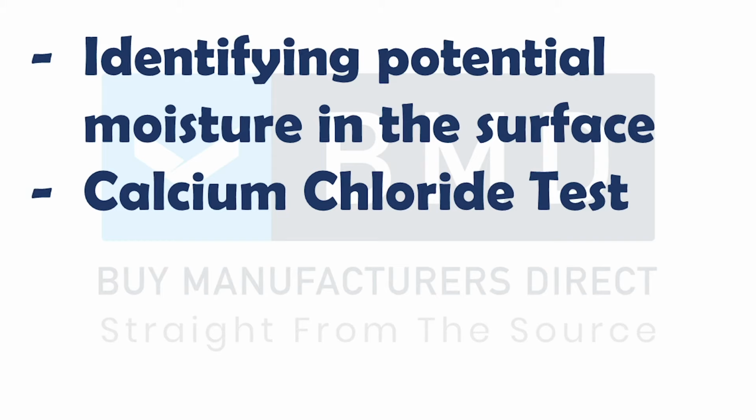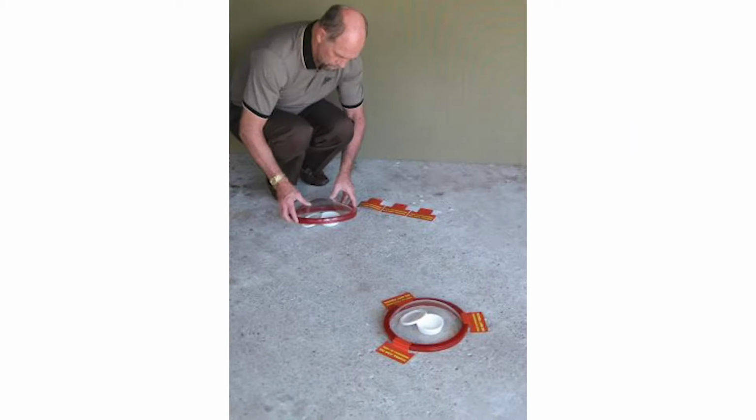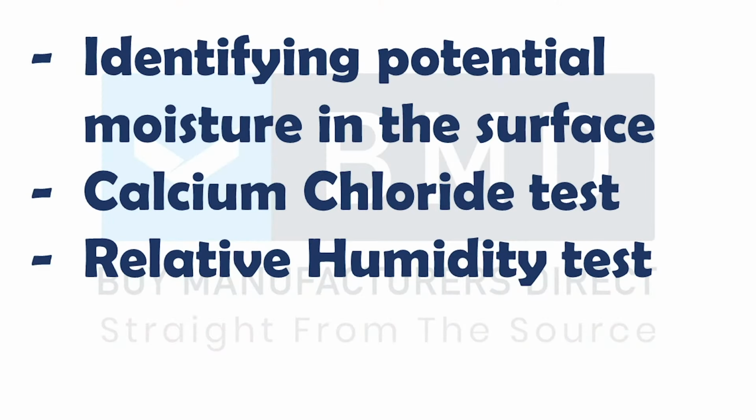The contractor should take it upon themselves to protect themselves, to test for moisture vapor evaporation rates, which is a calcium chloride test, a very old test. Some people will say it's too old and it doesn't work, it's archaic, but it does measure a certain amount of moisture vapor transmission over a time period. That is one insurance, let's say, against a future failure, that the contractor has at least empowered themselves with some information that before they poured it, they have an actual test that's been done that shows they've done some due diligence.